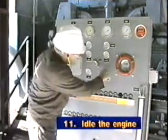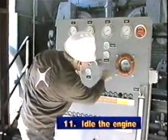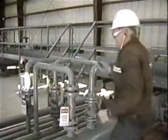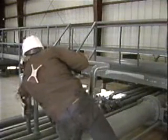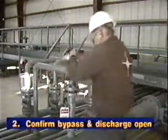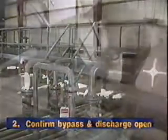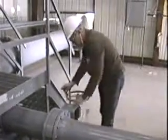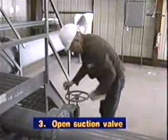Now idle the engine to check the coolant and lubricant circulation. The compressor is now ready for gas loading. First, close the vent valves. Then confirm that the bypass and discharge valves are still open. Now, open the suction valve.